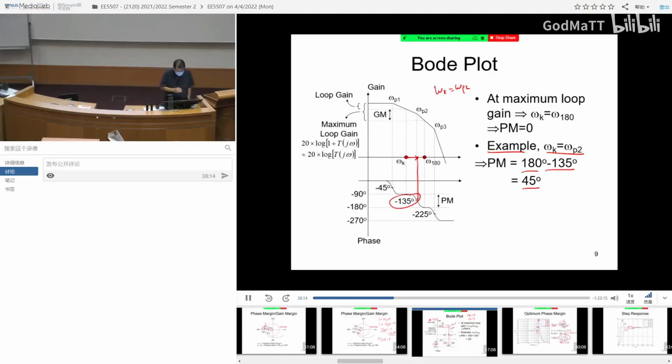Now in terms of the gain margin, you can also look up. So if you look at this guy, there is the magnitude. And then you can see how far this is from unity. Okay? This is the unity, so you can actually measure what this guy is, and that actually gives you the gain margin. Now this is the Bode plot.